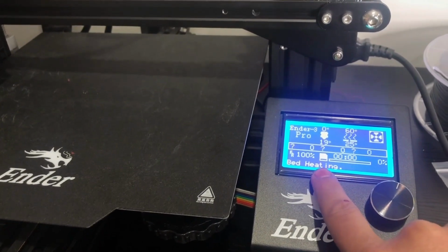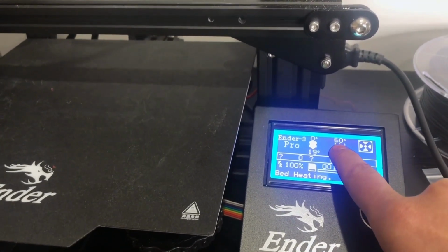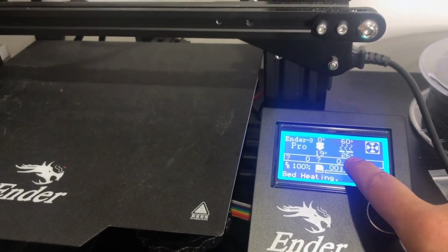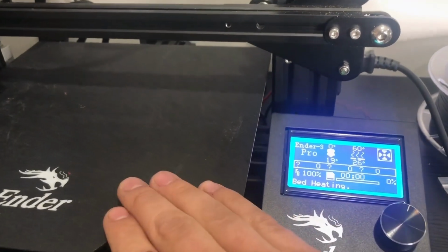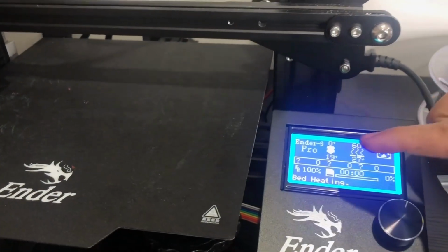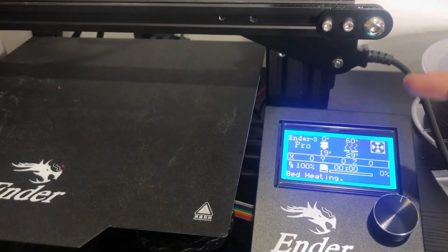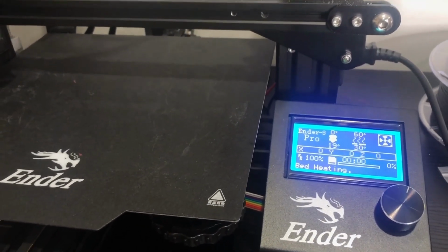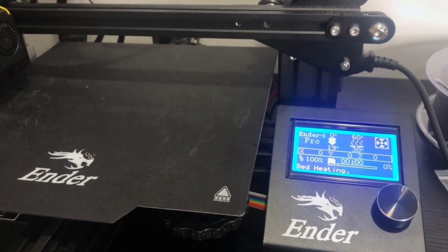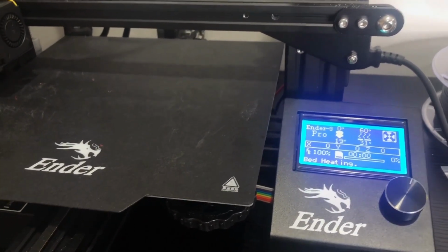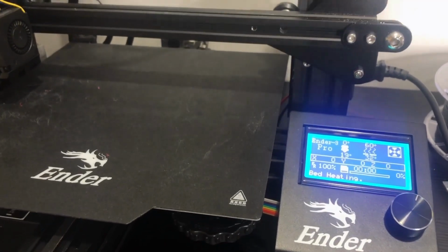So you can see the bed is heating up, and this is adjusted to 60. And then once the bed temperature actually reaches that 60 degrees Celsius, our extruder head will begin going up to 200 degrees Celsius. And then the print will initiate, as you guys will see in the next part of this video, as a time lapse, and see for yourselves the print and the file come to life.